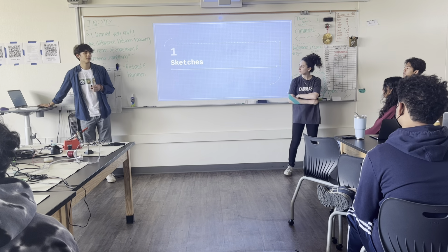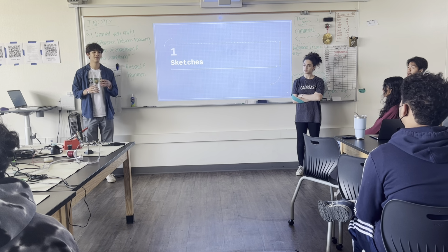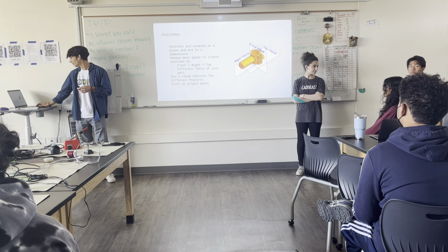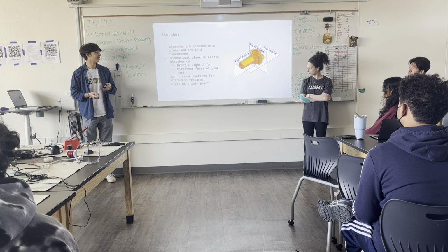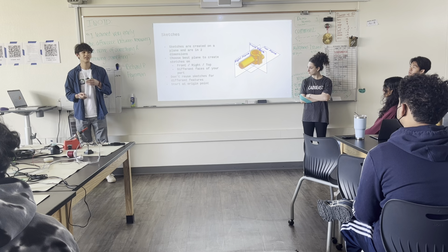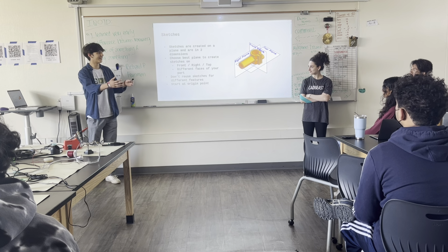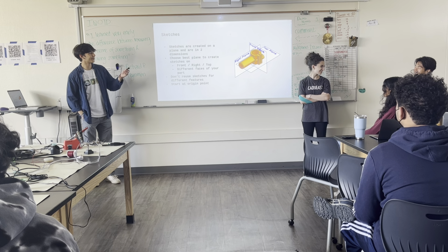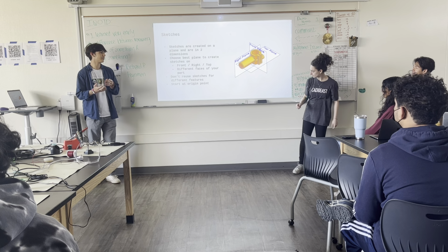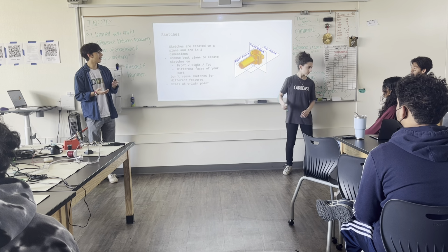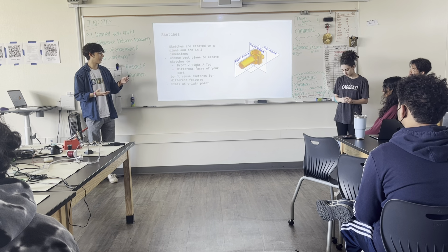And so the first thing we're going to go over is sketches. Sketching is a big part of CAD, and it's the backbone of any of your 3D creations. Sketches are created on a plane and are in 2 dimensions. So you first want to choose your best plane to do your sketch on. If you look at the model to your right, you can see that it comes with 3 planes, which is your front, top, and right plane. These are the bases. You can choose these to start off, and then you can also choose faces of your model that exist already to then make sketches on.